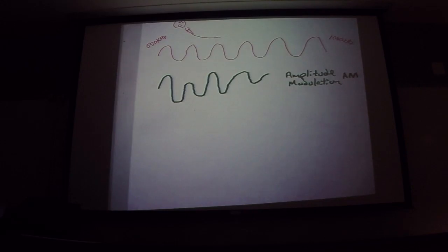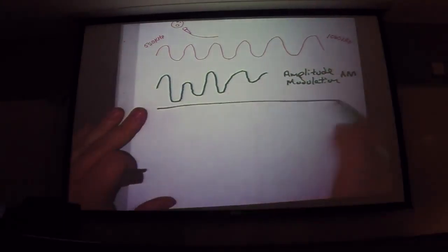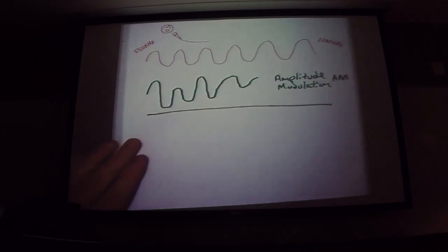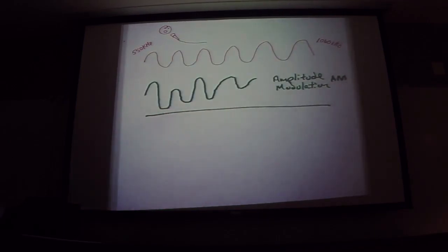So the second thing that you do is to modify the frequency. Now the problem with modifying the frequency is you need the frequency of stations to be far enough apart so there's room to modify it. So there's room to modify that frequency, which is why the FM stations have to have, there's no even numbers on your little FM dial, because they all have to at least give room so the other people can modify their frequency. The frequencies that you're modifying things by are in the order of thousands of hertz,